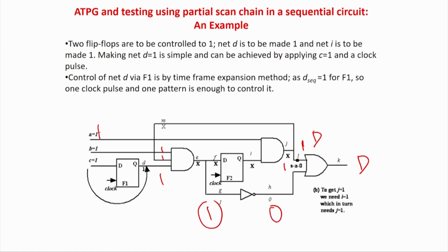So A has to be a 1, and of course this flip-flop has to be a 1. So basically you require a 1 at this flip-flop, and a 1 at this flip-flop. Very simply you do it, you will get the idea. Now you see that this is a cyclic flip-flop. I require a 1 over here, and this point basically is 1. This is a stuck-at fault.